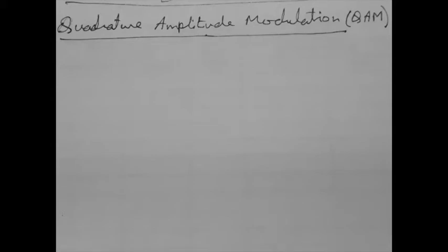This bandwidth can be efficiently utilized to transmit two independent message signals by slightly modifying the conventional DSB-SC scheme. This bandwidth conservation scheme enables two DSB-SC modulated waves to occupy the same transmission bandwidth, and yet it allows for separation of the two message signals at the receiver output.